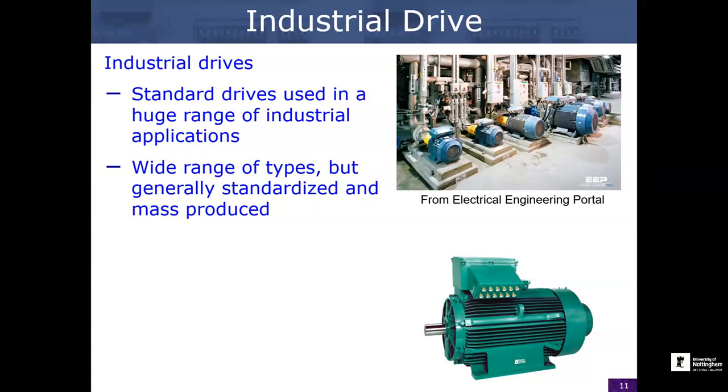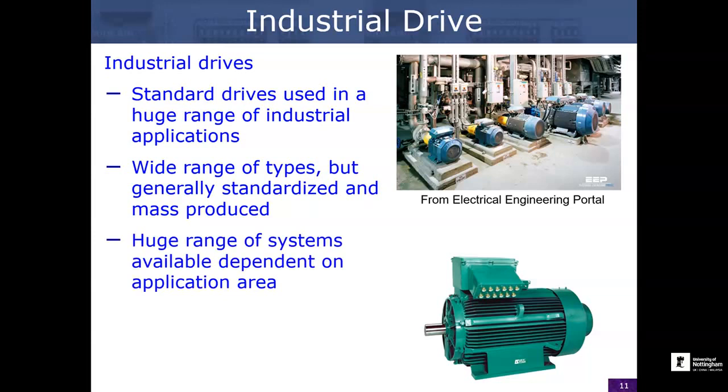So if you want, say, a 15 kilowatt drive for the UK, you could go to one of probably 200 manufacturers and they will have a standard 15 kilowatt, three-phase electrical machine, and they'll all have a very similar footprint and a very similar mounting type. They'll be competing on things like efficiency and performance and reliability, but these are to some extent standardized, so they're the kind of thing that you can buy in as a finished component and integrate into a larger system.